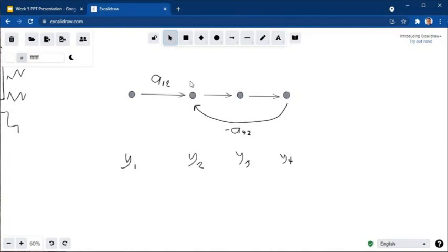Now, when it starts to measure that it's getting higher than 18, let's say it's now 20 again, that signal will be fed back to the system saying, hey, we are above the intended temperature. So it will produce cold air again, and so on and so forth. So that's the purpose of feedback. This one here is more likely a feedback signal. That's why we have reverse directions in our signal flow graph.